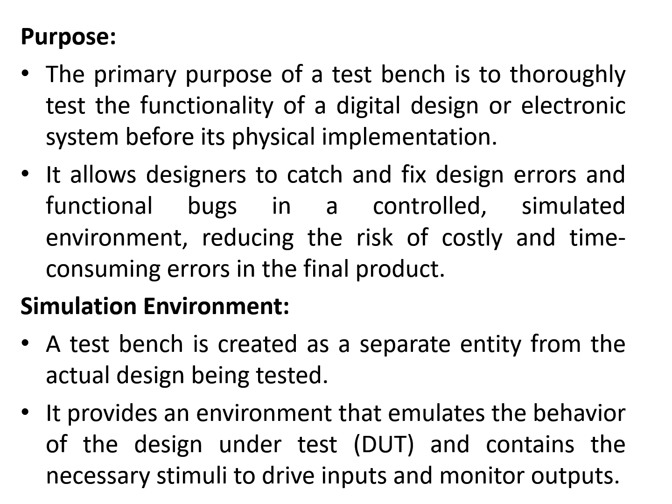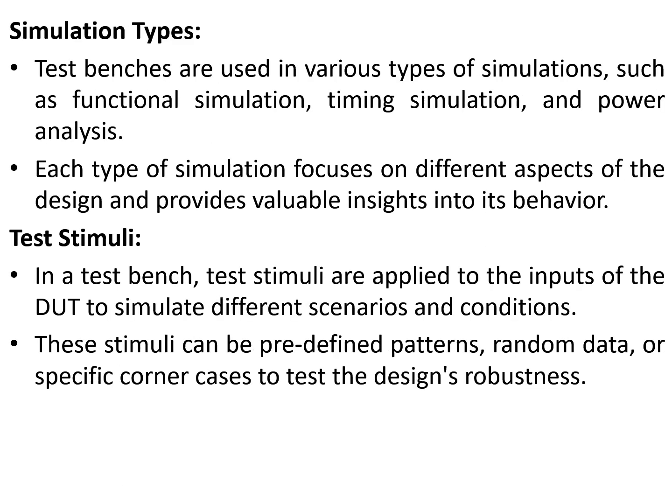Simulation environment. A test bench is created as a separate entity from the actual design that is being tested. It provides an environment that emulates the behavior of the design under test and contains the necessary stimuli to drive inputs and monitor the outputs.